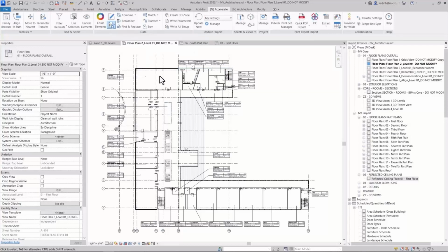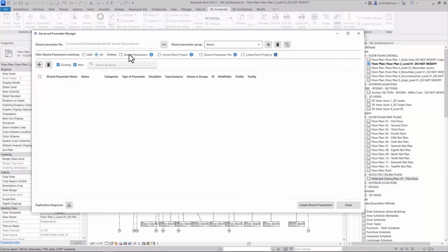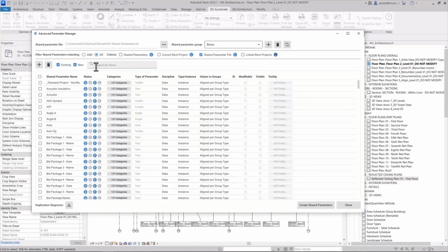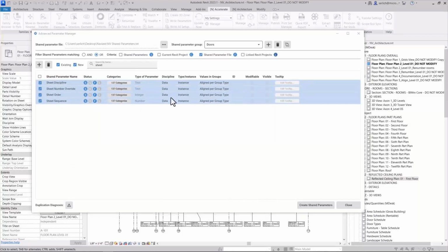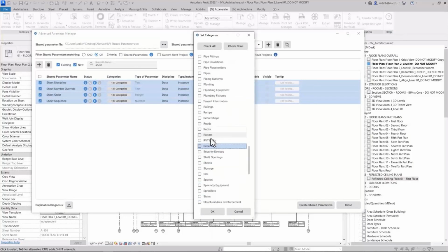This is the one I'm most excited to show you guys, which is the ability to batch create and manage your shared parameters. Here you can see I can select which shared parameter file to load, and then at the top I have a lot of filters. Once I start checking those filters on, I'll be able to see the parameters based off of those filters, and even do a search filter to narrow down my search to the parameters I want to create.